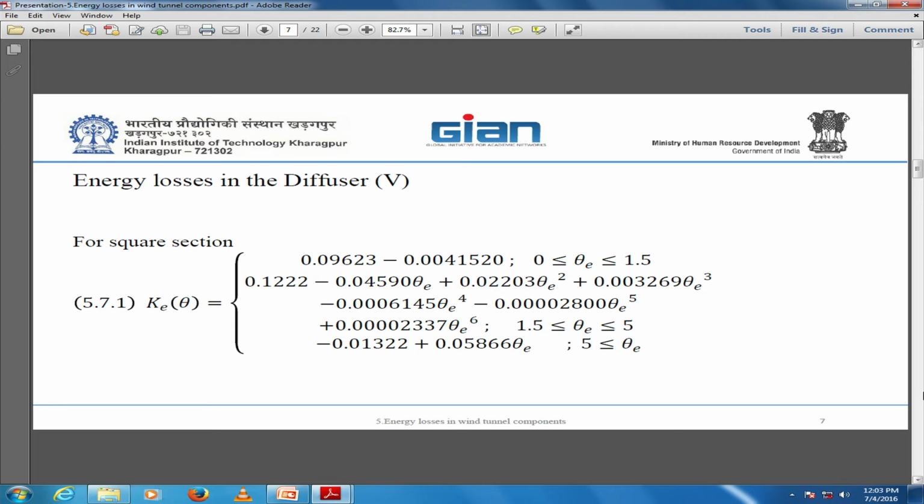They came to the conclusion that the best formula for the contour for the nozzle would be a polynomial of fifth power. There is a table in one of the papers showing that the fifth power polynomial is giving the best features in terms of separation and turbulence and uniformity of the velocity distribution.